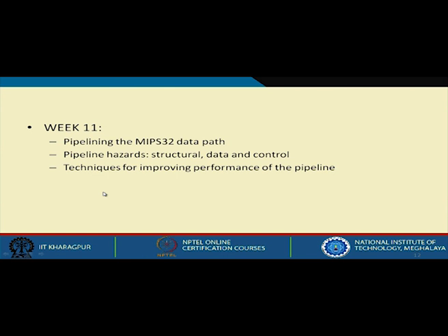Now, during week 11, we explored the MIPS32 data path again. So, earlier Dr. Datta discussed the hardware implementation of the MIPS32 instruction set, but here we just extended the discussion and discussed how we can implement MIPS32 instruction execution in a pipeline. Specifically, we talked about a 5-stage pipeline implementation. Because of the simplicity of the instruction set, the pipeline implementation is also seen to be very simple.